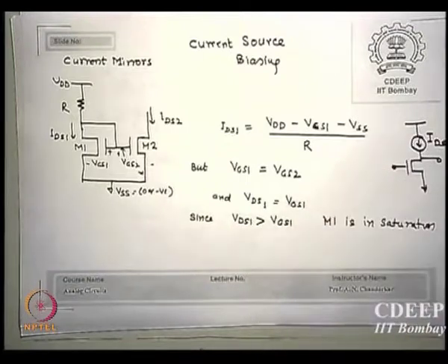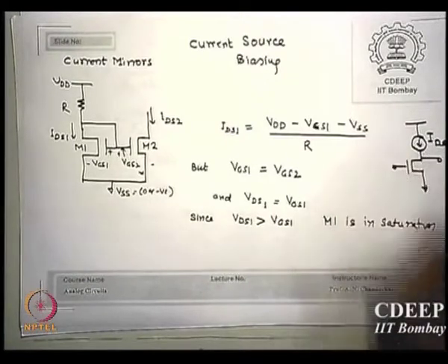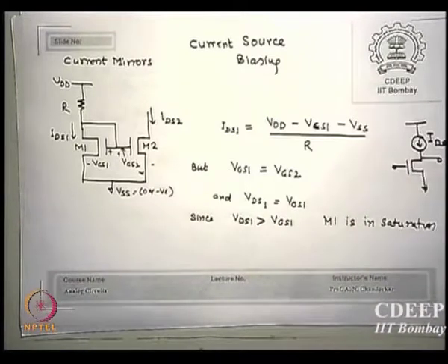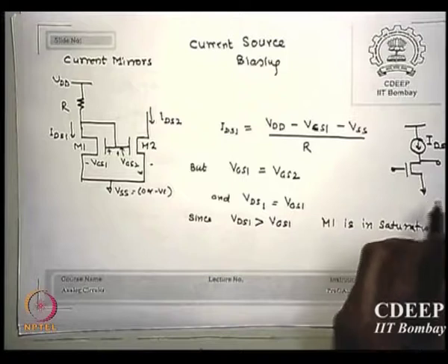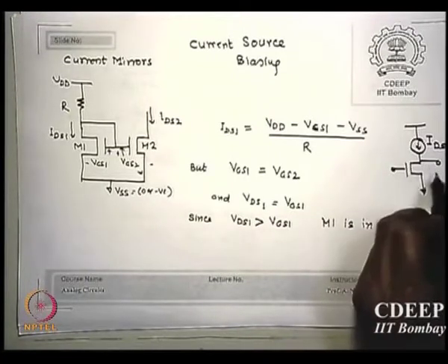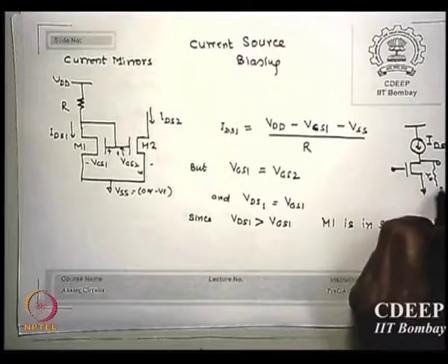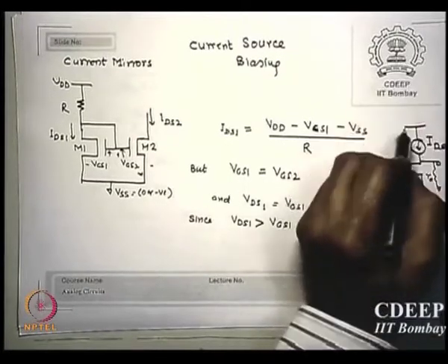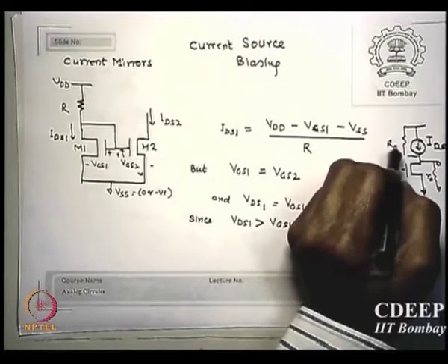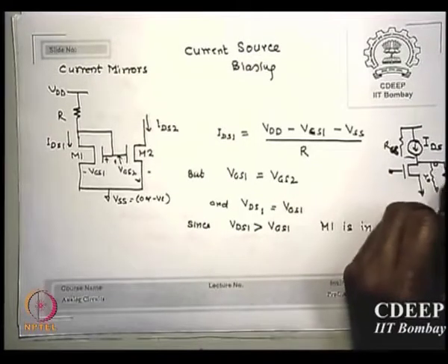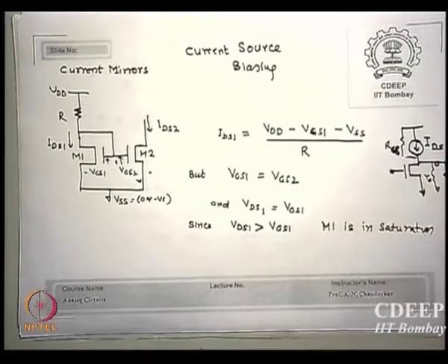What is the advantage of a current source? What is the resistance it will offer? The equivalent of infinity. What is the resistance across it? Infinite. Why I am worried about this is that some people initially were asking about r0, what is the output resistance of a MOS transistor? r0. See, in the equivalent circuit there will be r0 here, and the resistance of this current source, which I call RCS, will be shunted across it.